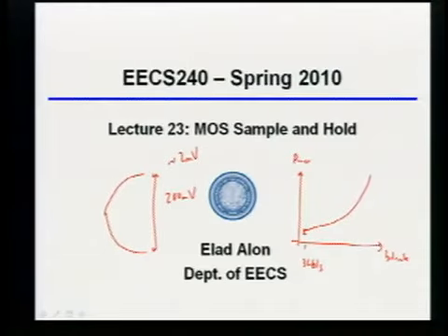By the way, just so that you know, people in real life have built links that operate at about 1 milliwatt per gigabit per second. And that's the entire link, including all the clocking and things like that we haven't really talked about, which we'll actually talk a little bit about next lecture. If you're hitting in that ballpark, that's pretty reasonable. In fact, because we're not doing things across process corners, you can probably even get a little bit better than that. More questions on the project? Must be more questions.